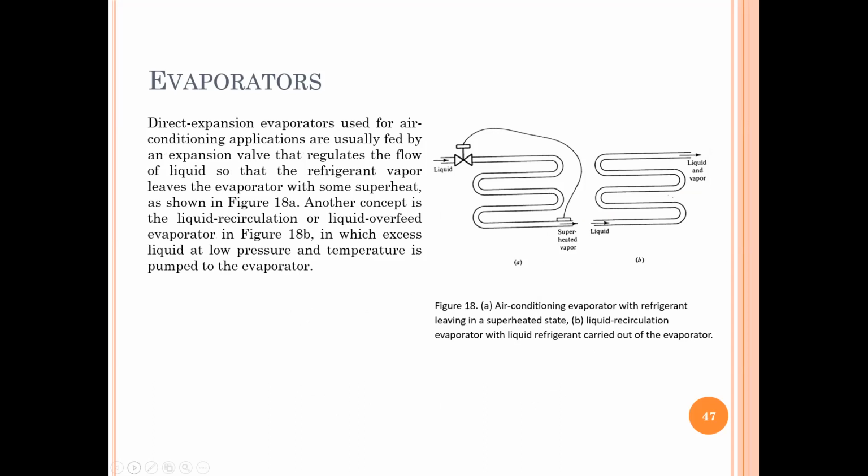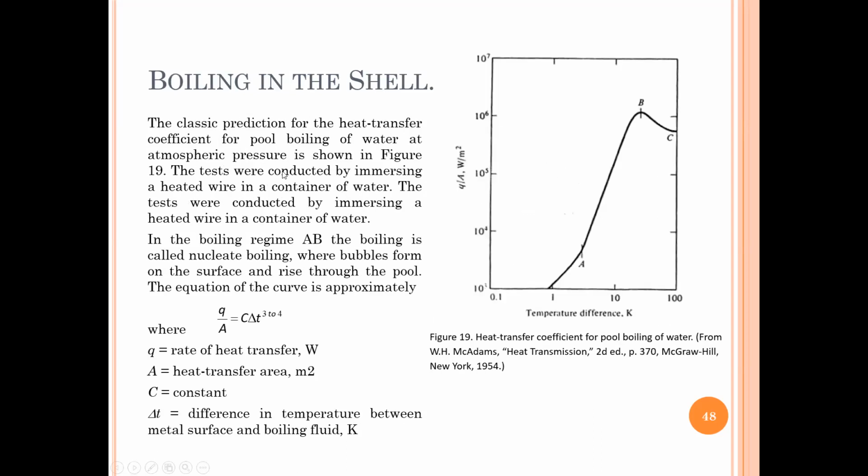Yes. Another concept is the liquid circulation or liquid overflow evaporator in figure 18B, in which excess liquid at low pressure and temperature is pumped to the evaporator. Now, boiling in shell. So, ito yung evaporator. Nagbo-boil, di ba? The classic prediction for the heat transfer coefficient for pool boiling of water at atmospheric pressure is shown in figure 19. The tests were conducted by immersing a heated wire in a container of water.